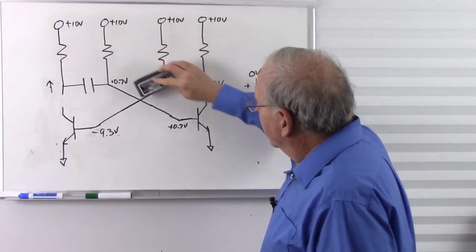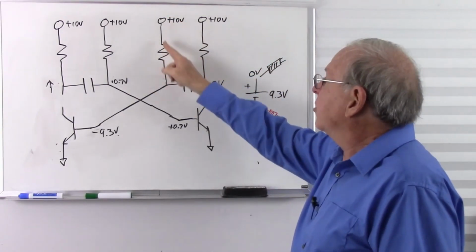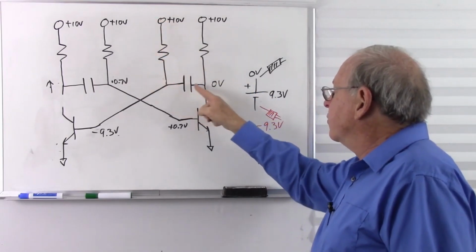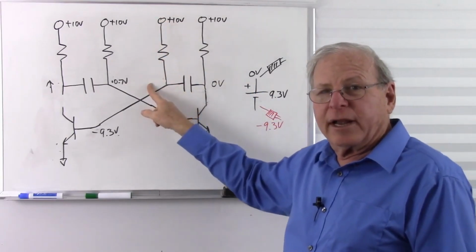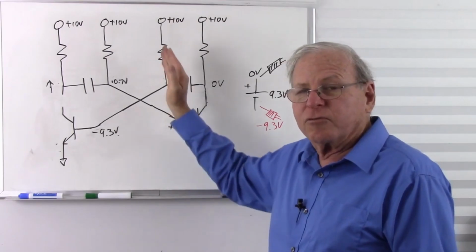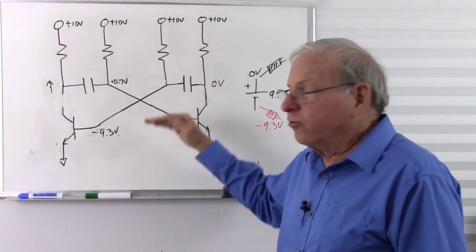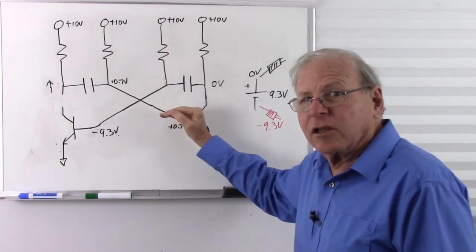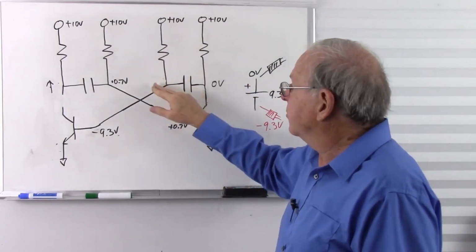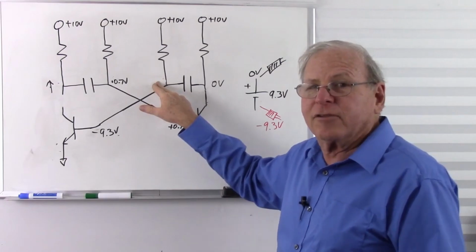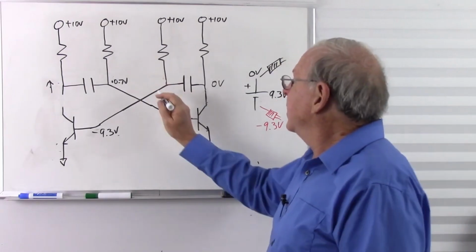So what's it going to do? That voltage is going to go up. So this is charging just like before. The current is going this direction. That's charging. It starts at minus 9.3 volts and the voltage just rises. Negative voltage is not the opposite of positive voltage. It's just lower. So we went lower voltage. It's going to take a little longer to charge up, but it's going to charge up. It's going to hit 0 volts. It's going to keep on charging until what?